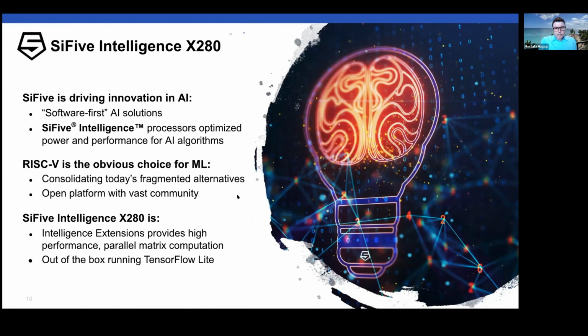So the X280 includes all the vector instructions. Yes, the X280 fully implements RISC-V Vectors 1.0, the standard instruction set. For ML tasks, it can also be done with a subset of the extension.